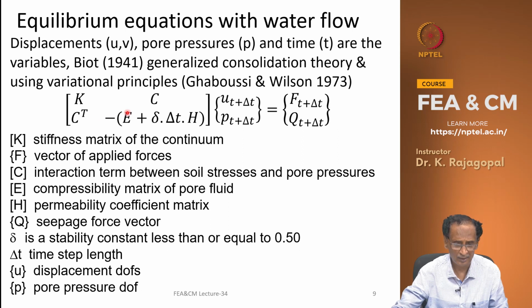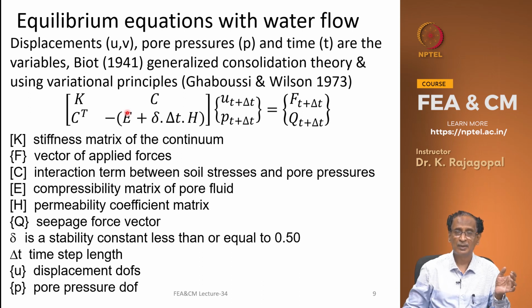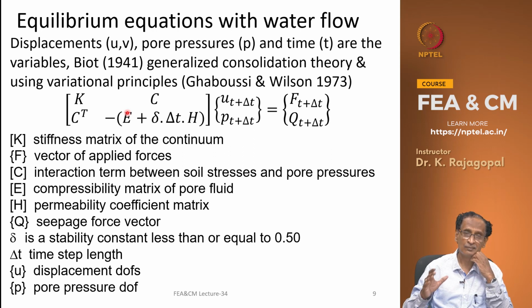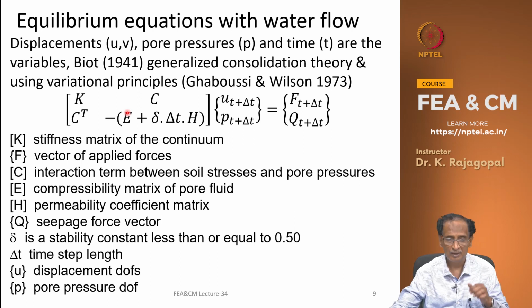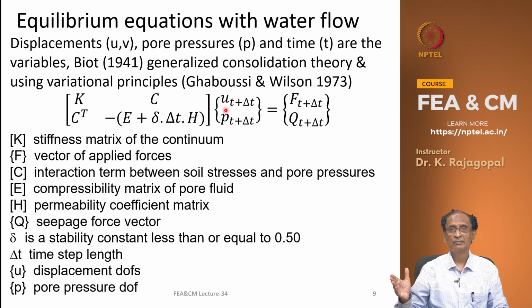We can come out with the equilibrium equations for the stresses or the forces, and then based on the continuity equation, where the flow into the volume is equal to the flow out of the volume, or if there is a compressibility, we can include that in our continuity equation, and we can derive this equation where u is the displacement vector, p is the pore pressure, and t plus delta t refers to the next time step.